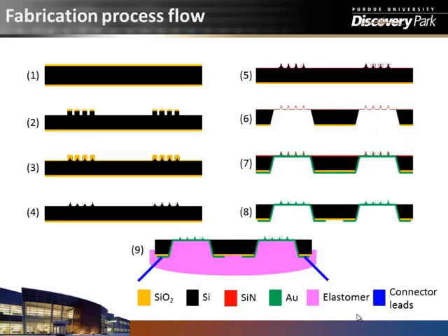So we went ahead and fabricated these devices. We started with a high resistivity silicon wafer, oxidized on both sides using a thermal oxidation process. We then, using lithography and an etch process, made micropillars. There was oxide on top. And then we oxidized this surface, and that gives us a selective oxidation, which, when we remove the oxide, yields silicon tips that are very sharp at the tip. This is an established technique, although it's difficult to understand why this happens, but there is selectivity, and the oxide grows faster towards the tip as compared to the side of that pillar. So you end up with these sharp tips.